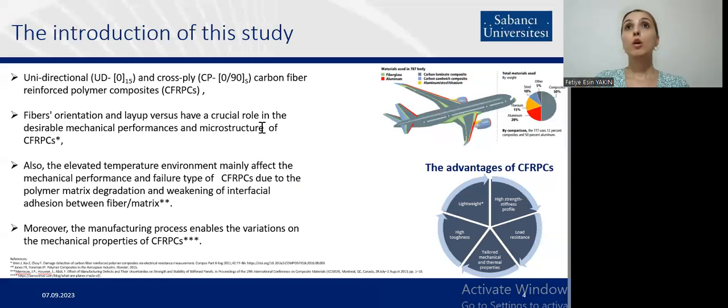However, vacuum bag only is a great candidate as an alternative to autoclave curing, because autoclave curing has a lot of drawbacks such as being time consuming, energy consuming, and having final part size limitation. Vacuum bag only is a great candidate for getting the final composite part. However, it should be investigated by adding some kind of parameters.